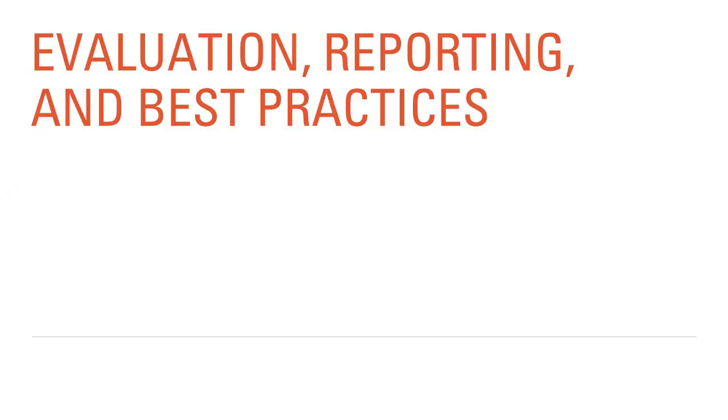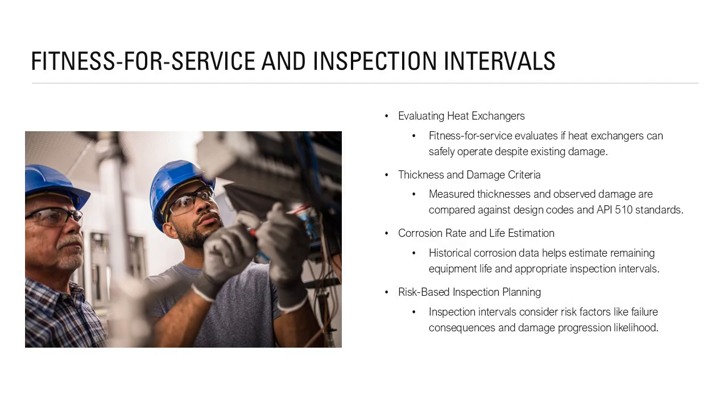Fitness for service and inspection intervals, documentation, inspector competency, and summary. Fitness for service evaluation is used to determine whether a heat exchanger can continue operating safely with identified damage. Inspectors compare measured thicknesses and observed damage against minimum required values derived from design codes and API 510 criteria.